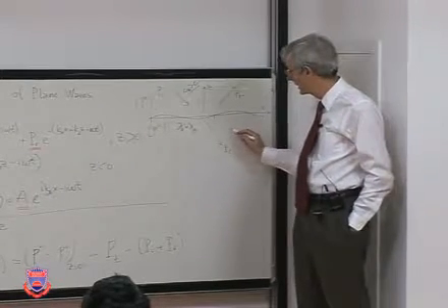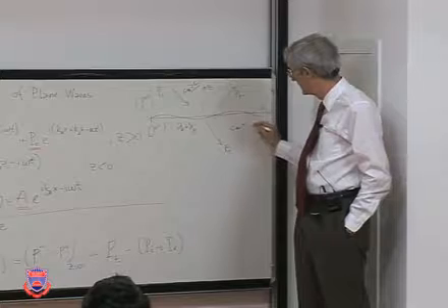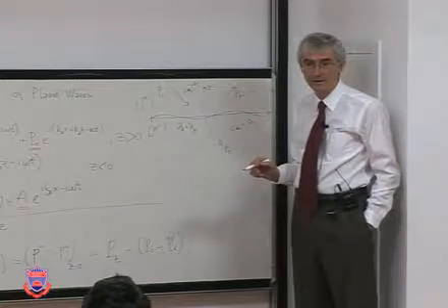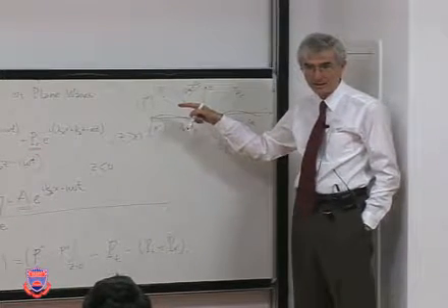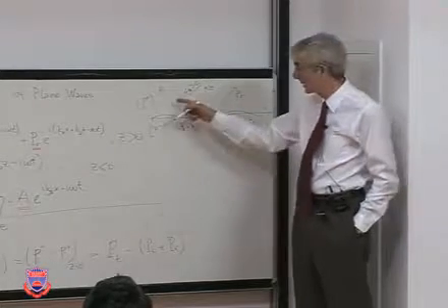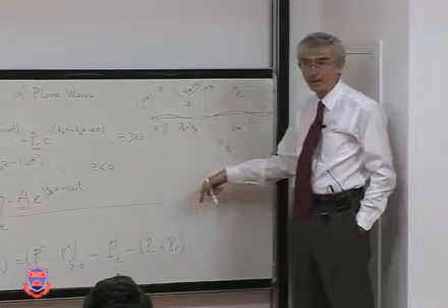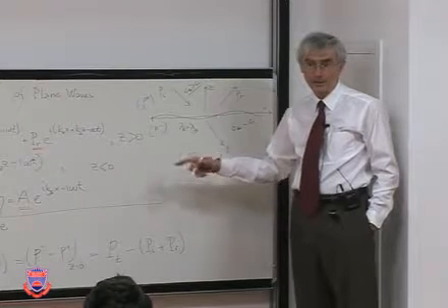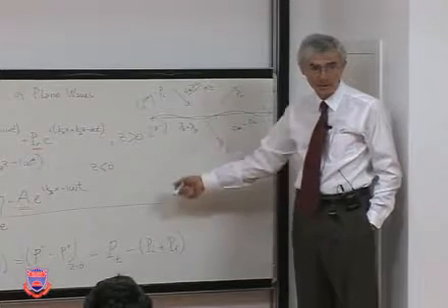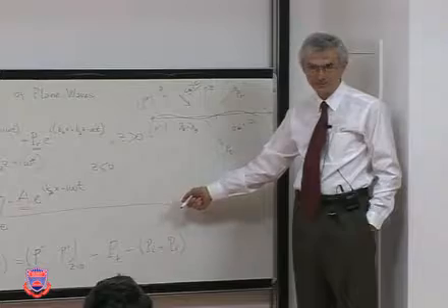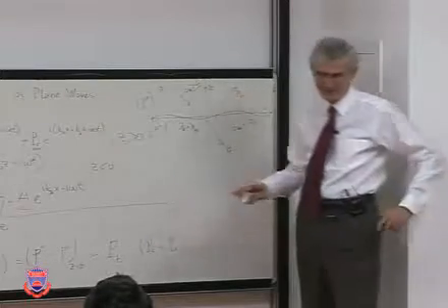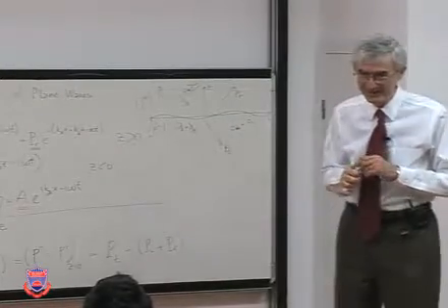But that may not be the case here, because sound is coming from the other side. So there may be a case where the excited sound may not radiate to the other side because its bending wave speed is smaller than the speed of sound there. Does that make sense? Is it complicated?